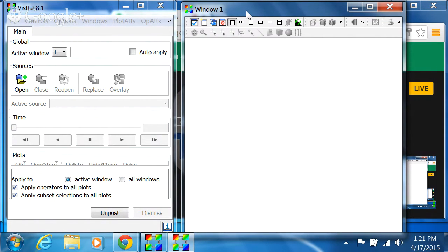So the same scripting capability is also in VisIt. You can capture and record all your mouse clicks. Every mouse click on the GUI can be turned into a Python script that you can automate. The reason is you can run it without the GUI and use the supercomputer, get 32 cores, however many nodes you need, and then generate your images. Then you can bring it in, start playing with different angles, how you want to create a movie, and then you click a button, and you've got a movie. So this is what they do. Okay.